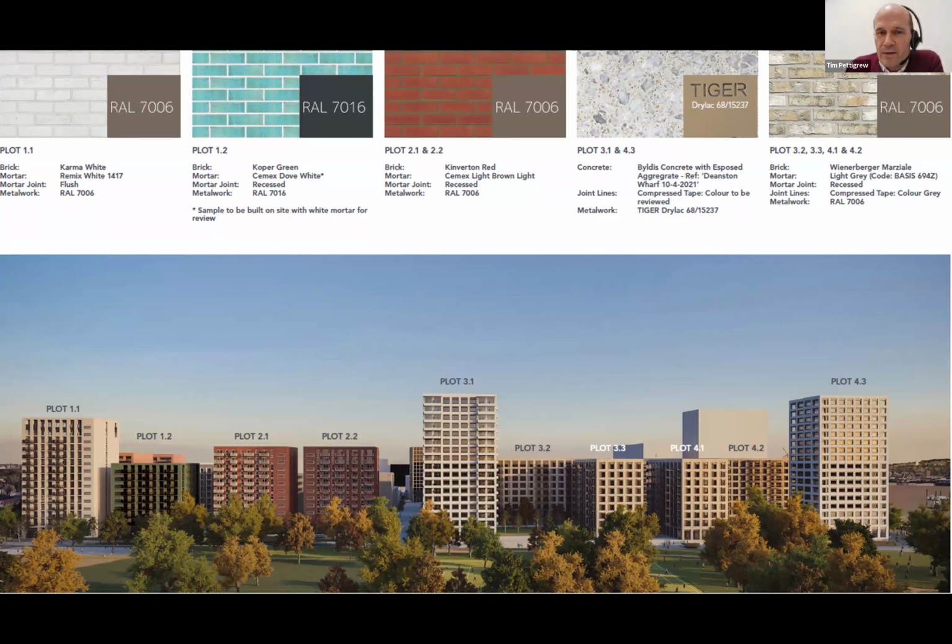In essence, each of these blocks was able to be installed by 3 people and a crane operator at about a floor a week. So it's a very safe system, and there are some specific benefits to this one, which is why we chose it for this area. Now, in terms of the 10 buildings that we've developed, the 6 on the right-hand side from plot 3.1 to the end were all done using the Builder system. The others were produced through a traditional system, and it was quite interesting to see the two methods being done at the same time and being able to compare.